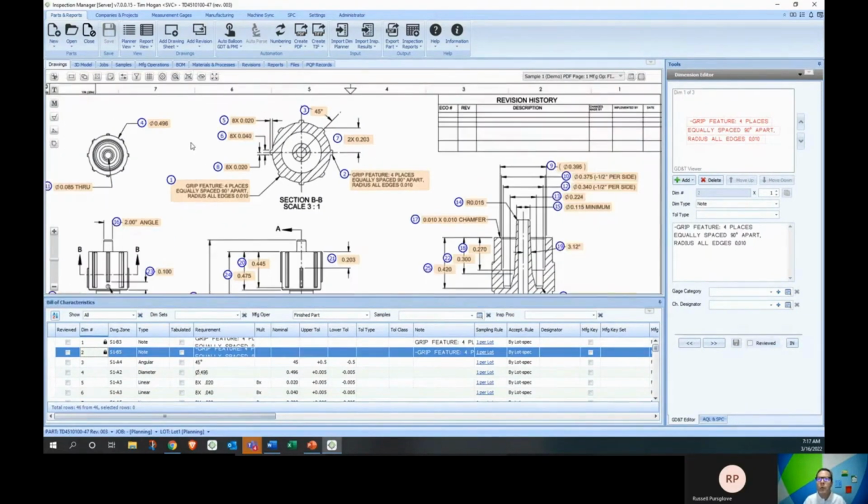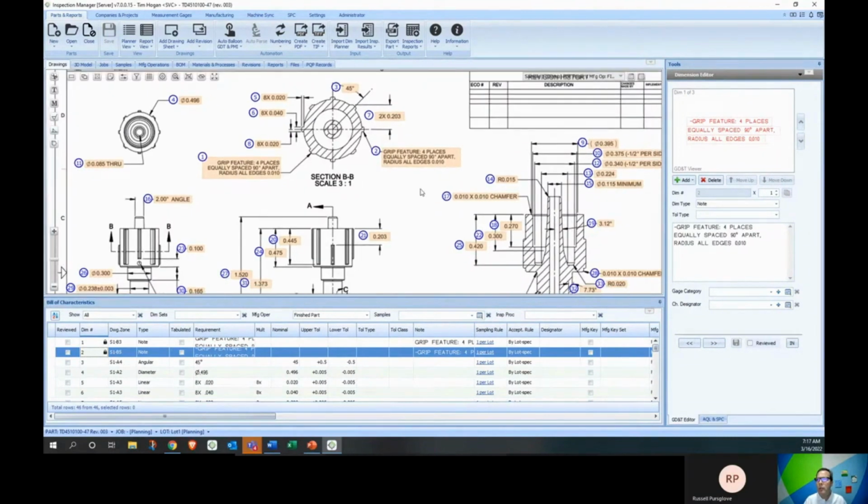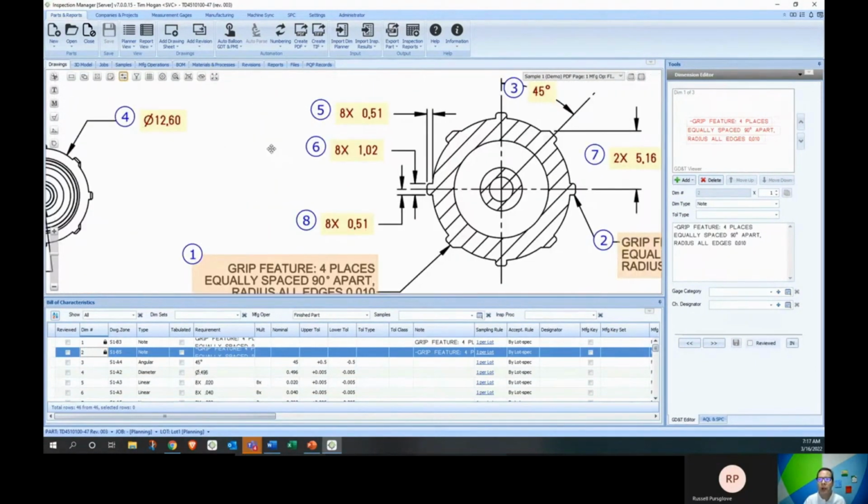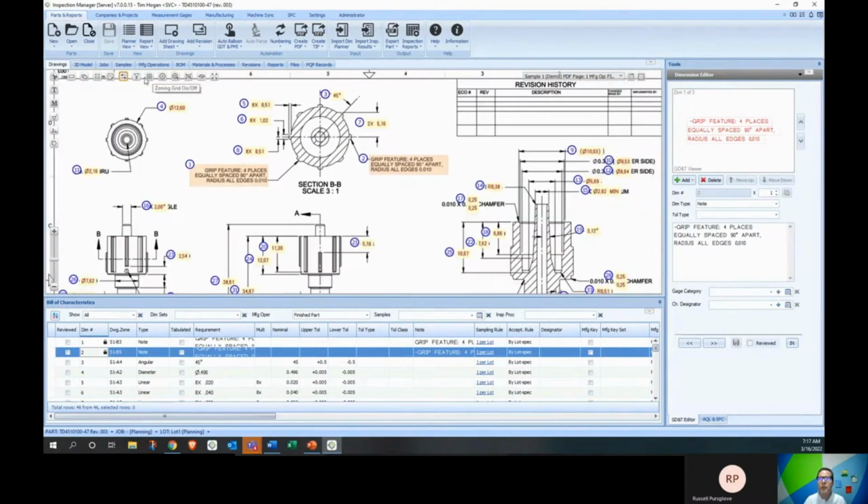I don't know if any of you get some crazy prints that are in inches instead of metric. If that's the case, as in this print, we can simply come up here to our convert option, and it converts it into the other unit of whatever is there. So that's sometimes a convenient option if you get the wrong scale prints, if you'd like.